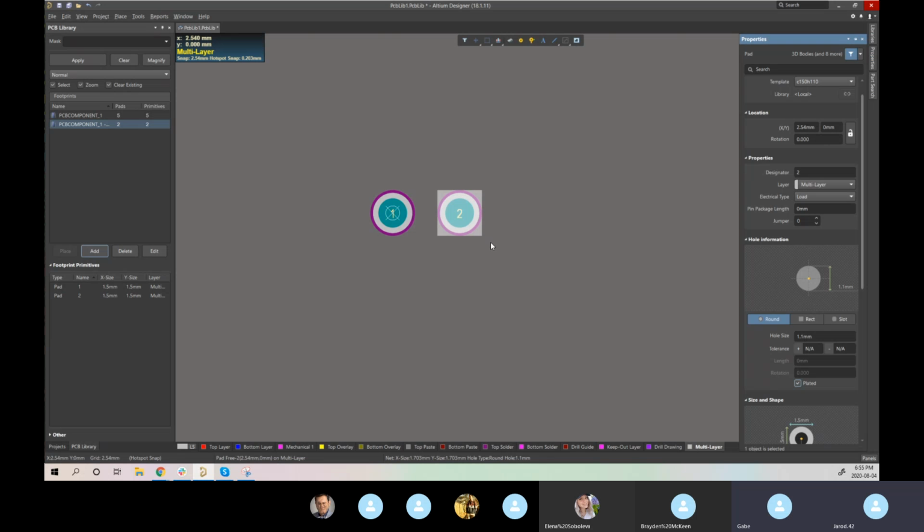I guess that's one way, once you start getting into high-speed design, by not plating your holes, you can get rid of the stubs in your design, which are known to be bad for high speed and EMI. But that is way beyond our workings. So for the most part, we keep these plated because we want connection through and through.